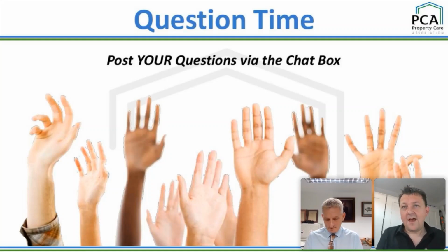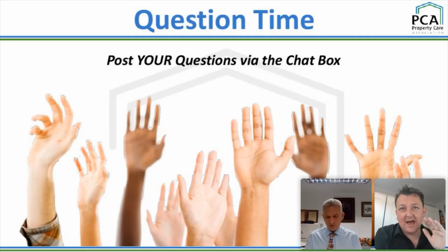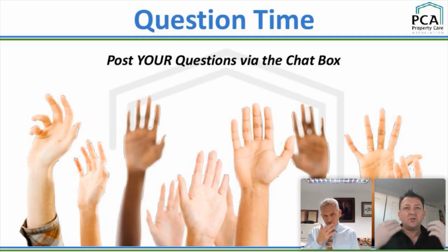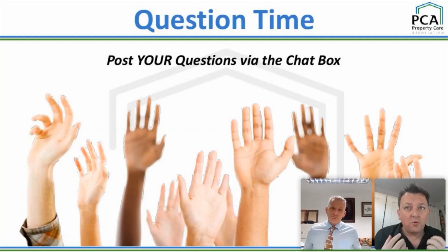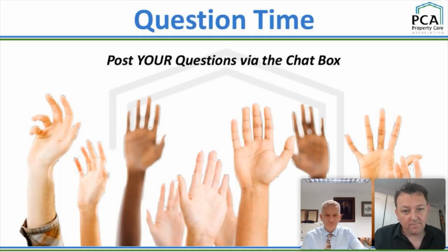All right. Well, I'm coming to the last of the questions. I think I've got enough time to pose. I'm grouping a question here, both from Aziz and Patrick Harvey. It's to do with movement joints. Should retrofitted movement joints always be fitted to internal leafs as well? No. If you read the guidance, long stretches of internal walls should have movement joints. I have installed one for ages, and I've not seen a negative result of not doing.